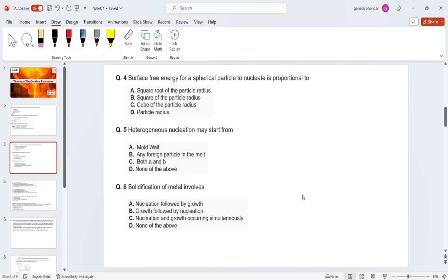So what we can do is pour molten tin at 400, 500, 600 degrees on a copper surface or some other surface, just measure the contact angle, and from that contact angle relationship you can see how the wettability of that particular surface is changing. The more the wettability, the more it will spread onto the surface, and the more it spreads, the more diffusion there will be. So by that you can see the correlation.